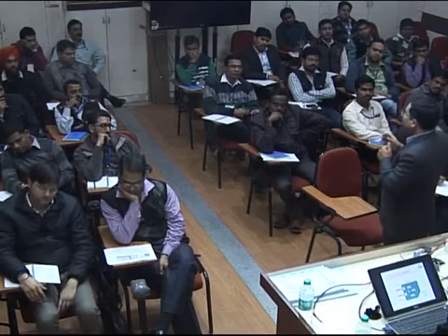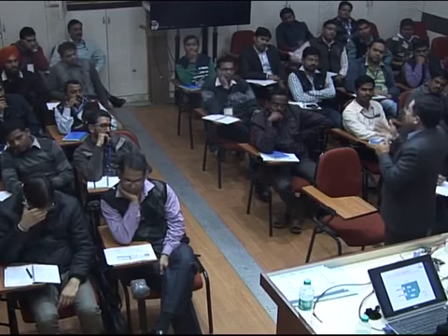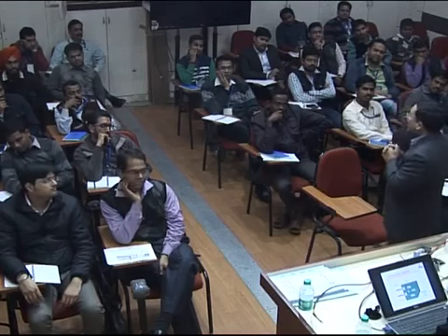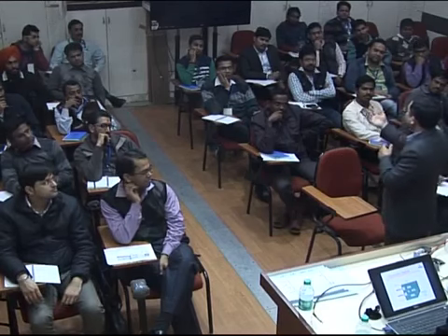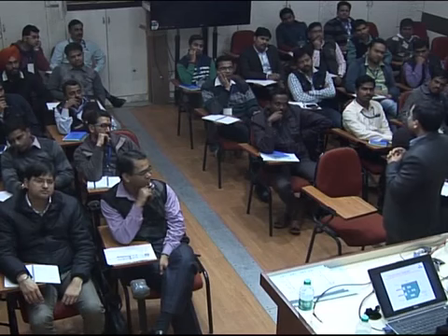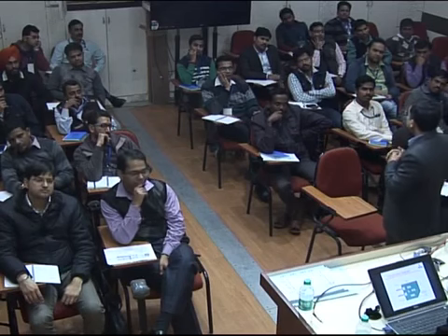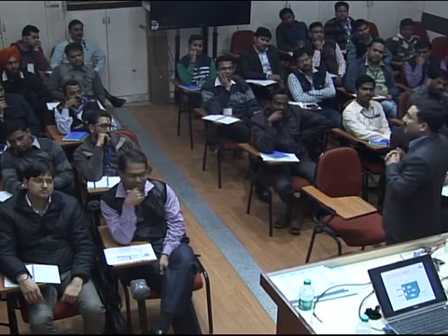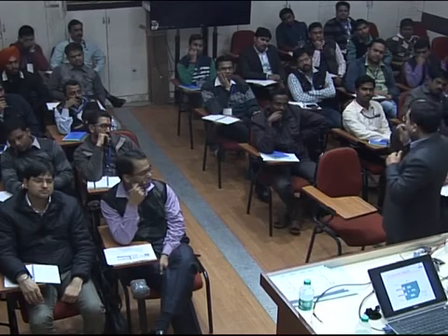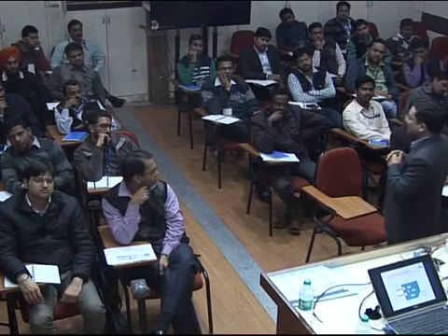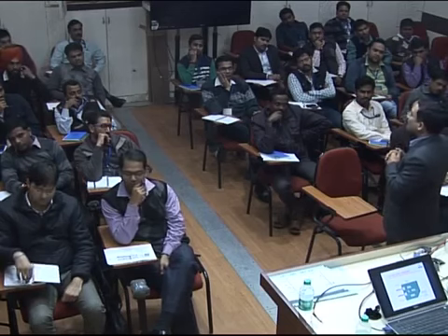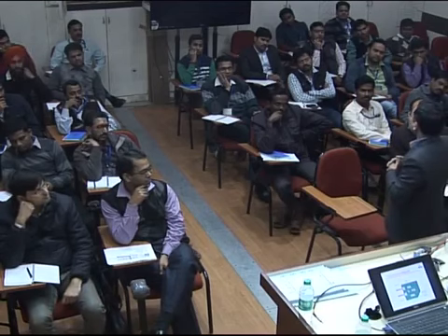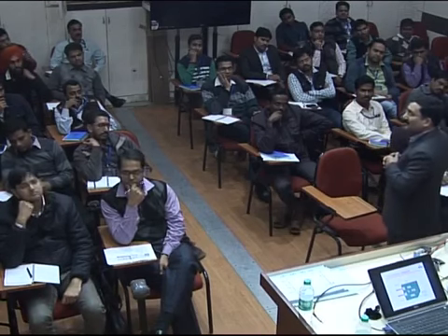And even two sensors sitting side by side, as Dr. Jha is provoking everybody to think, light from one may get into the other, both being at 20 kilohertz. So mind it, no two sensors are switched at the same frequency. In our production line, every sensor is slightly tweaked to be different. Maybe once in a blue moon, in different production lots, some frequency may be numerically the same. But no two sensors would be switching at the same frequency ever.